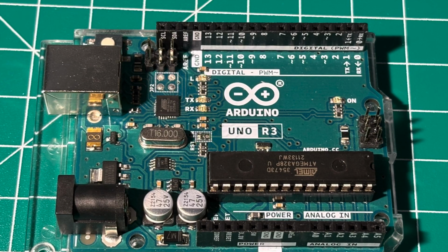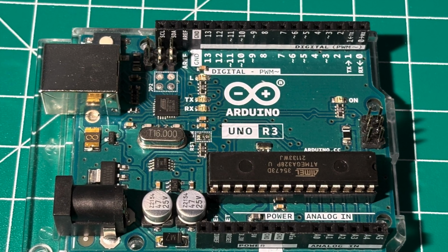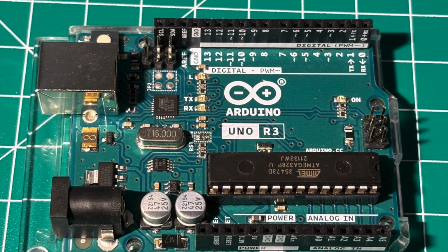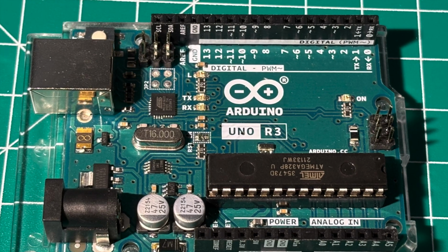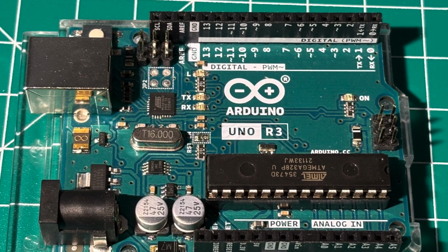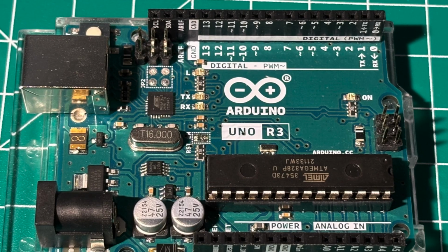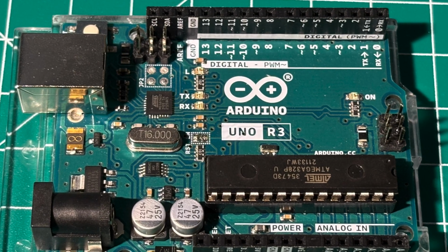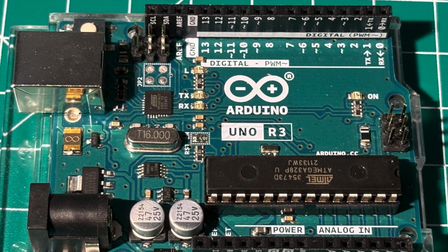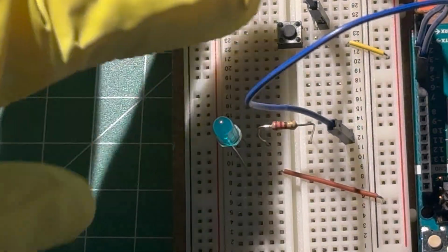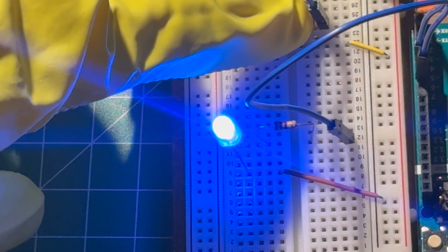While this system is rather simple, the implications of such an attack are extensive. With increased system complexity, we may not even be able to detect malicious firmware during normal operations. Further, to prevent the board from being read out from or written to, fuse bits in the bootloader would need to be modified. This is a feature that has to be done manually by the developer. Otherwise, this attack vector will remain present.